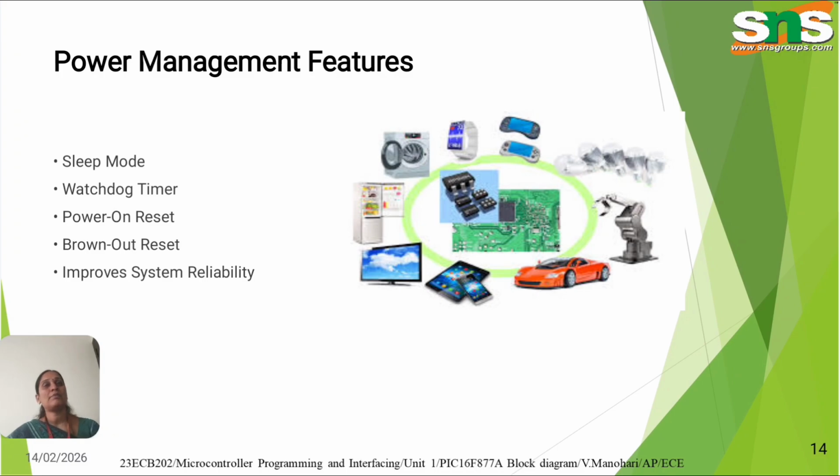Moving on to the power management unit. It includes power saving features like sleep mode, watchdog timer, power on reset, and brownout reset. It reduces the power consumption. The watchdog timer resets the system if the program hangs. This improves reliability in real-time applications.